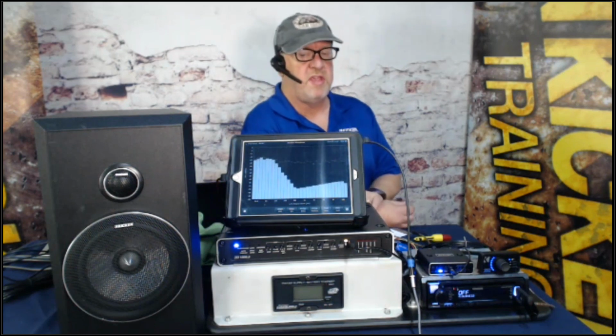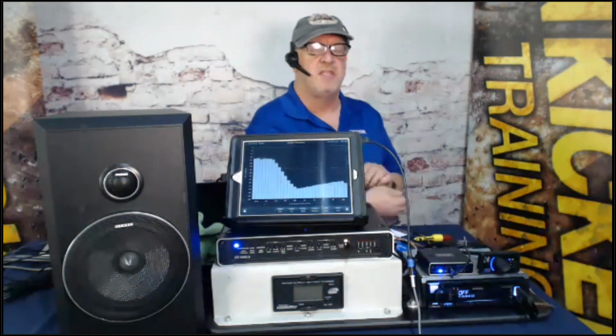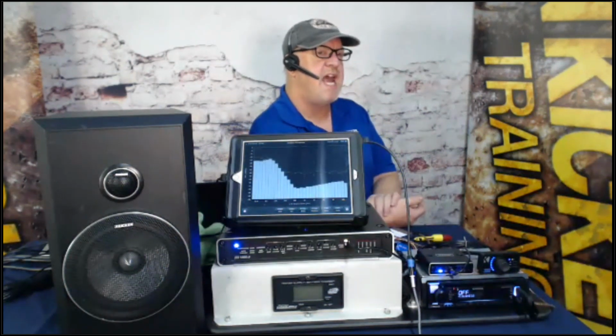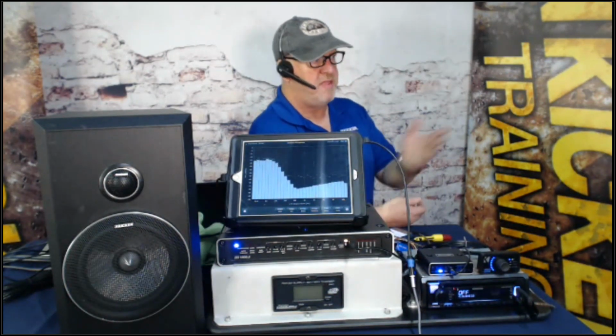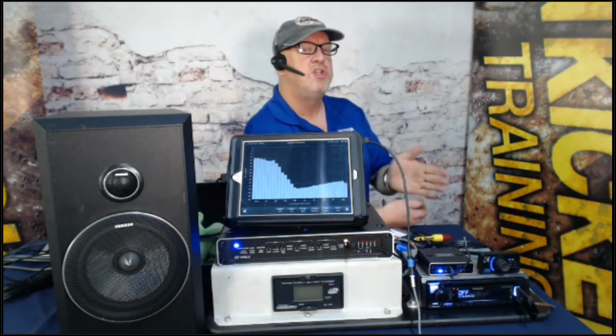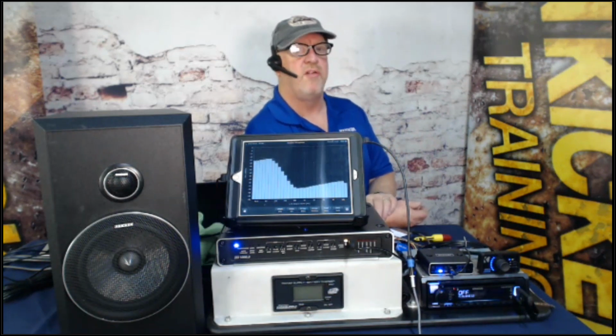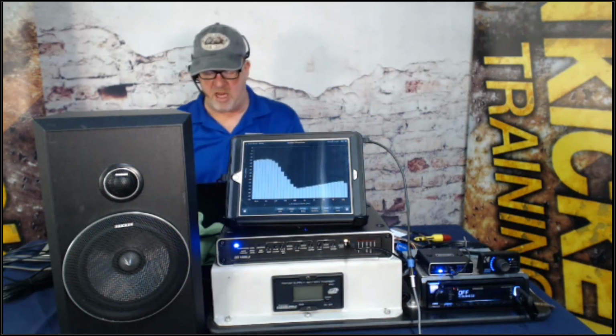Now, low pass crossover, you see it's starting to roll off the high frequencies, and I still pass the low frequencies. If I'm just adding a subwoofer to a stock system, and this is the signal, as long as the frequency is higher than what you're going to cross over the aftermarket equipment at, you can use this to just add a subwoofer. But if you try to use this for a full range signal, it's not going to be adequate.